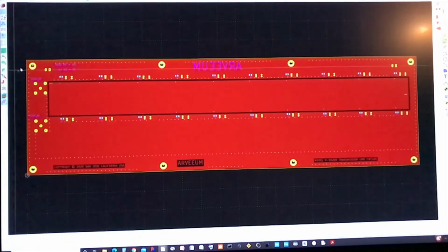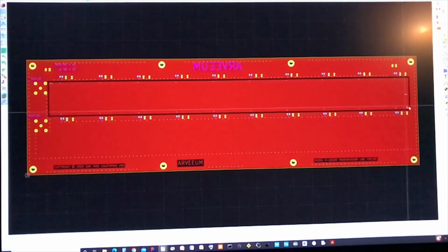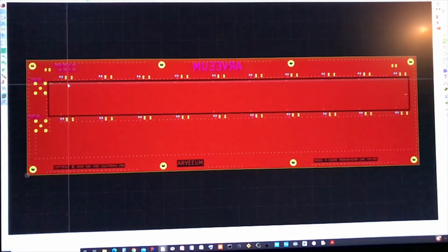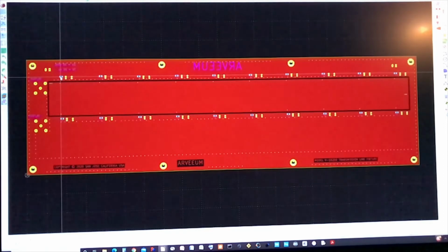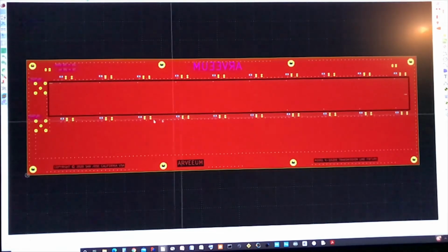So this one has a moat all around it, but it is possible to provide a path for the currents to return to the main plane by using these caps that are all around that cutout plane. And it's possible, by closing the switches that are in these pads here, and thus the current can move from here through the cap to the ground and the plane.